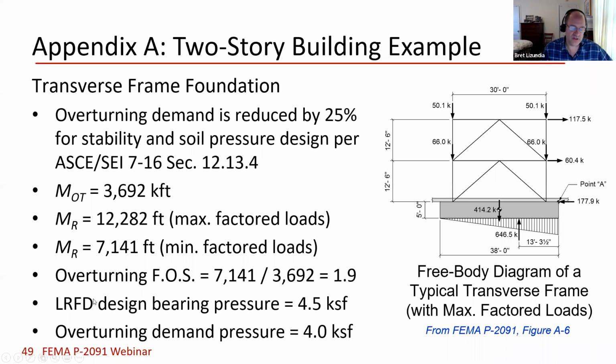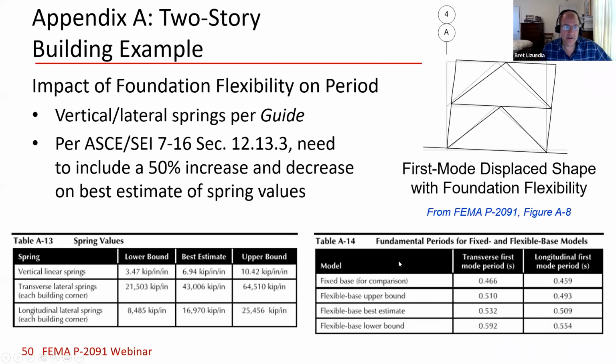He was doing this at the LRFD level. It's a little unusual. A lot of foundation work is typically done at ASD, so you have to reduce your LRFD earthquake loads down to ASD values, but you don't have to. If you have an LRFD capacity from your geotechnical engineer, then you don't have to do that.